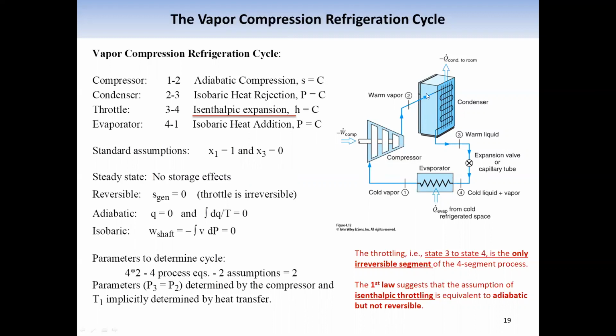This heat release includes the pump power and the heat absorbed from the cold zone. Then the fluid returns to the cold zone through a nozzle or an expansion valve. So the fluid expands and then absorbs the heat, returns to the compressor and releases the heat.